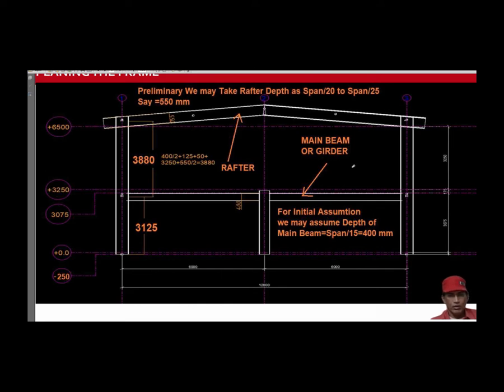So many times we do not use chapter 12, and instead we actually reduce the response reduction factor parameter in seismic loading and keep this value around 3 or 4 as per ordinary moment resisting frame or ordinary concentric braced frame. Thus actual seismic loading is increased by 33% or 66%.